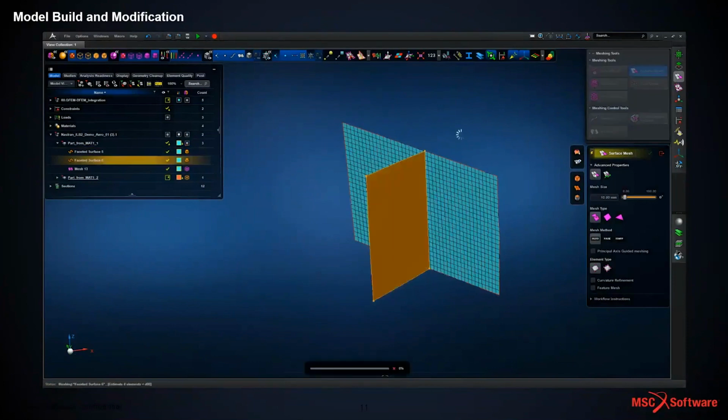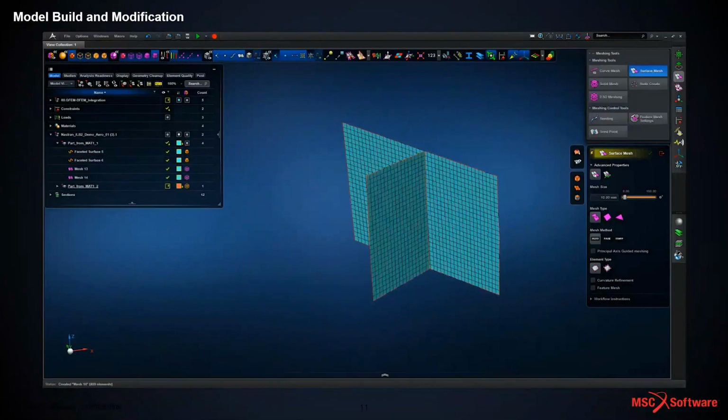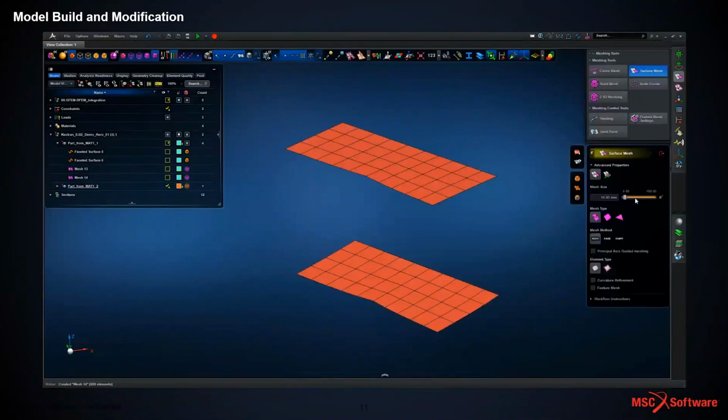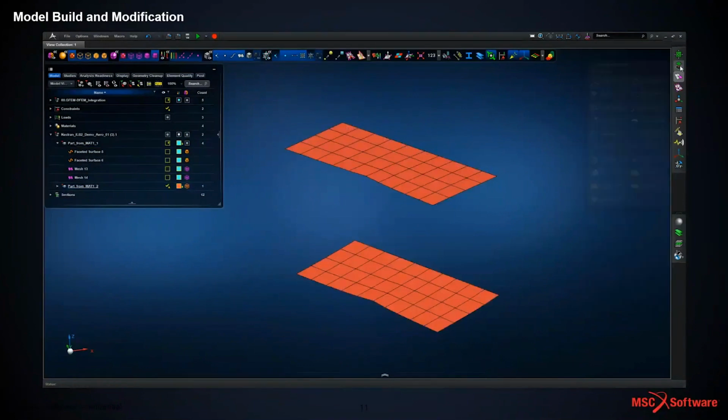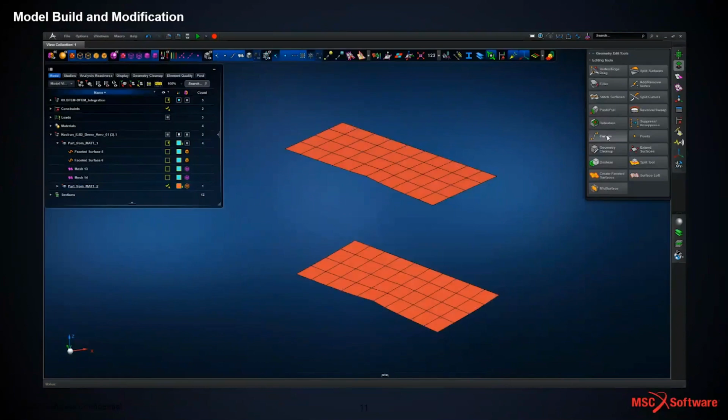One point to say here is that we're looking at flat surfaces. This is equally valid for curved or spherical type surfaces. So we've created the orphan mesh for the spar and wing rib. In terms of the wing cover, or the covers, the upper and lower covers, we're going to take a slightly different approach now. We're going to use some of the other geometry-based tools. So we're going to create a series of curves that pass through the edges of the mesh.